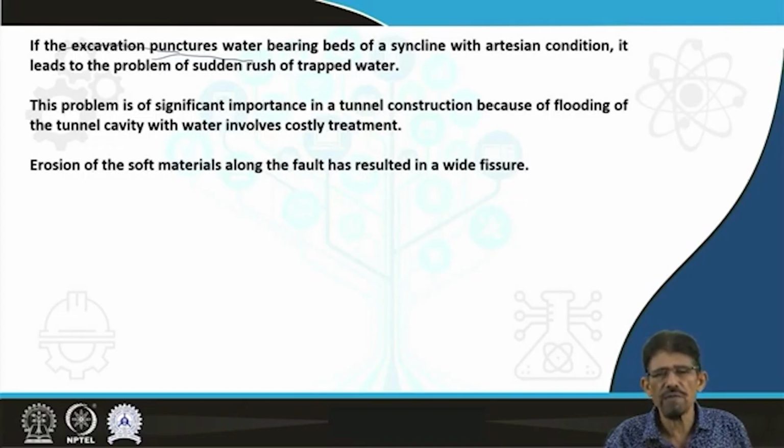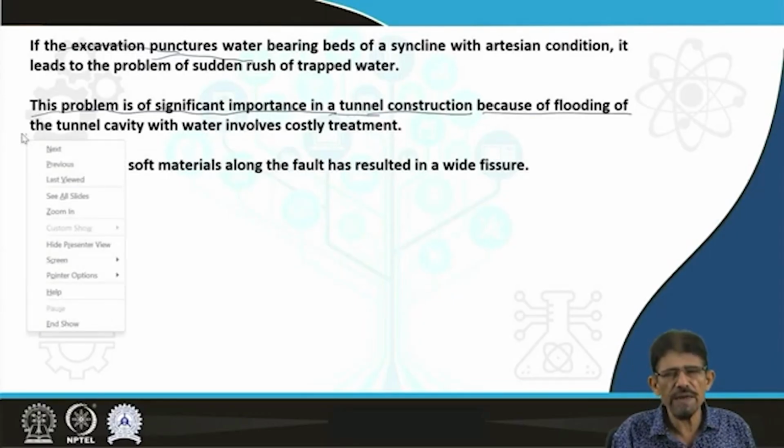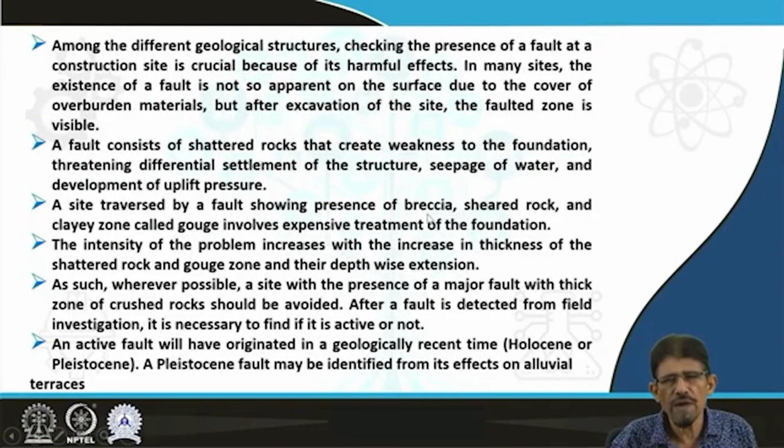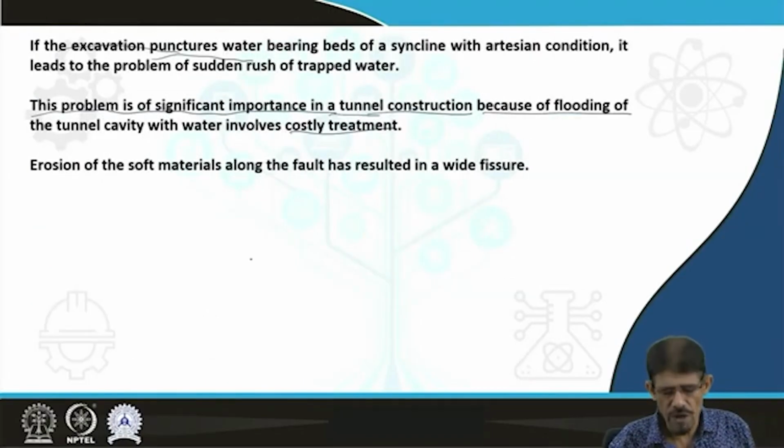That confined aquifer system is going to push the structures and rocks, and make the whole site disturbed in nature, causing an increase in price of the project and delay in work. This problem is significantly important in tunnel construction because of the flooding in tunnels, creating delay and increase in cost of project in the form of costly treatments and others.